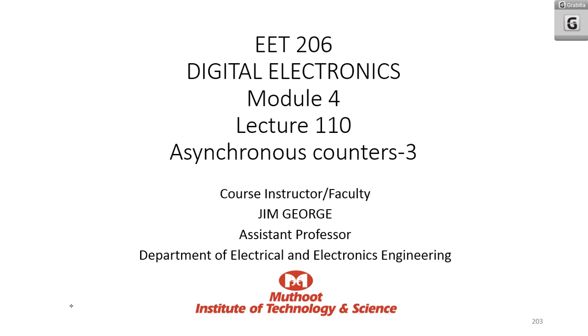In this lecture, we are going to deal with asynchronous counters. So what basically are asynchronous counters? They depend on a specific modulus. That is, here I am going to design an asynchronous counter so that it can count from 0 to 5, for example. It can count from 0 to 10 or 0 to 12 or 0 to 15, like that. That means it is basically a modulus counter.